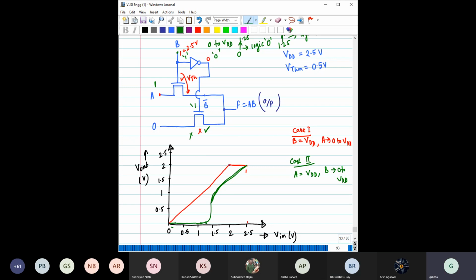Very good point. Why do you think so? Sir, VDS, drain to source voltage, not threshold voltage. Oh, drain to source voltage. Okay, drain to source voltage will also change. So as a result I think it will shift from saturation to linear. Okay. Do you also think there is a possibility that the threshold voltage will also change?